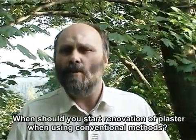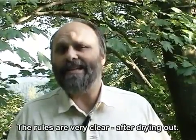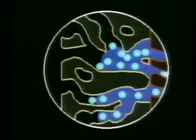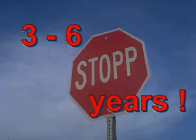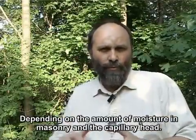When should you start renovation of plaster when using conventional methods? The rules are very clear. After drying out. Why? Very simple. When moisture is evaporating through masonry, dissolved salts are transported as well. These would move into the new plaster and destroy it from the inside by clogging it. This usually takes about 3 to 6 years, depending upon the amount of moisture in masonry and the capillary head.